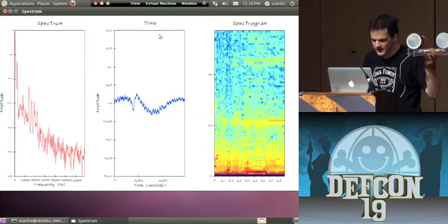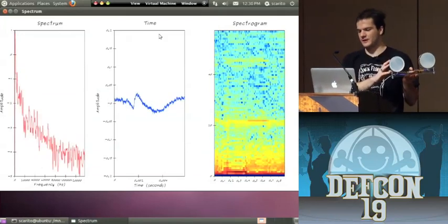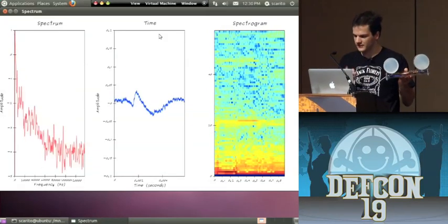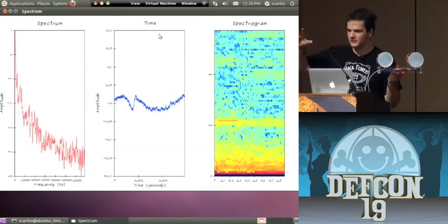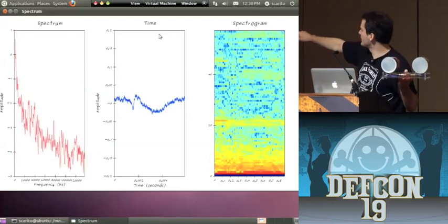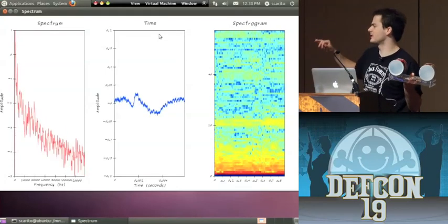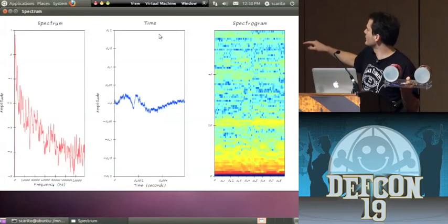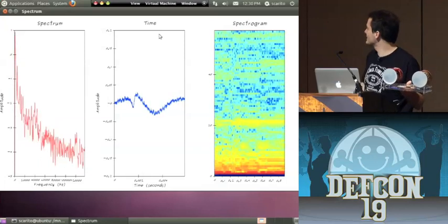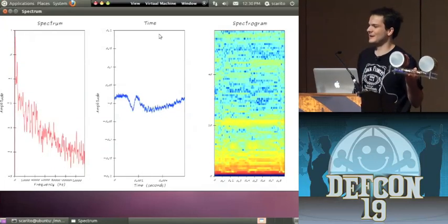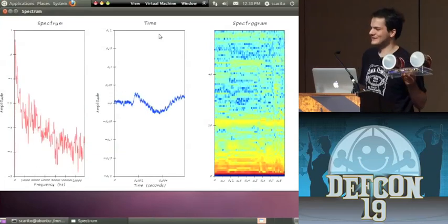And the other thing, which I haven't actually seen yet, which I'm a little surprised by, is that this thing operates in the Wi-Fi band. And there's a lot of noise. I'm not exactly sure why that's happening. That wasn't happening before. But what you do see occasionally is these pulses towards the top end of that. And that's actually Wi-Fi signal bursts from the thing transmitting. I think it's a 20 megahertz wide signal. And what you see for that is a little pulse in the middle of the time window. And unfortunately, I guess no one's using Wi-Fi devices in here because I'm not picking anything up. So I guess everyone's being smart now and they're not using Wi-Fi at DEFCON.